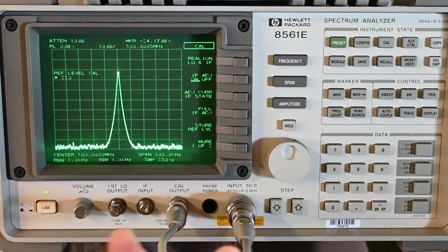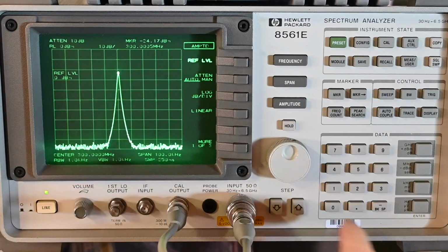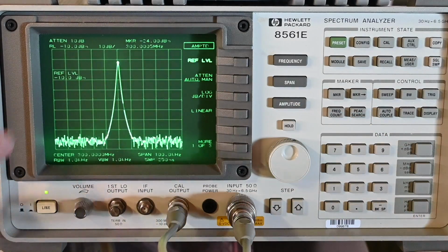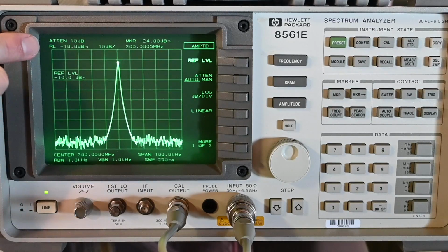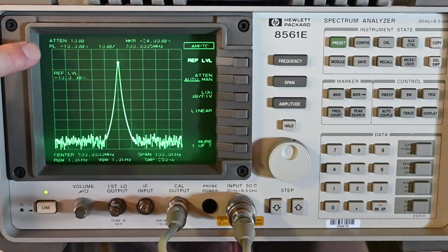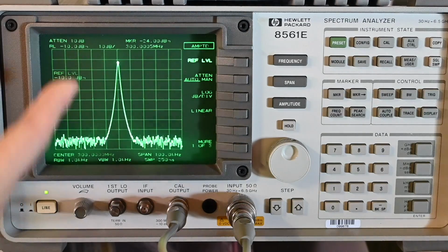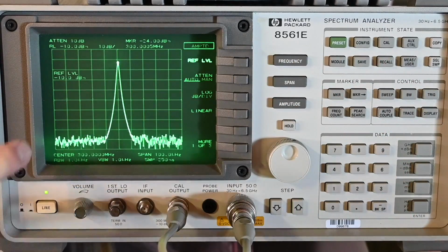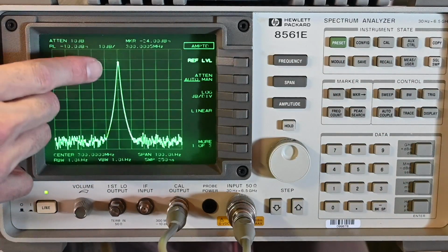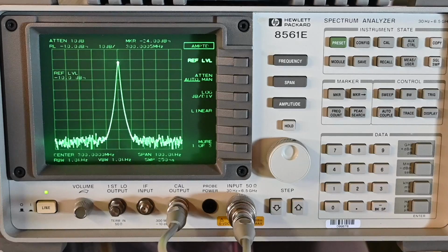10 dBm. In fact, what we can do right now is if I go to the amplitude and the reference level, see if I step it down right now, reference level minus 10 dBm, see how it's still shy of touching the top? So now the top graticule going across right there, where it says RL, minus 10 dBm, it should be touching the top, but it's not. And changing that value in that cal menu, it does not have enough range to bring that all the way up. So something is definitely wrong.